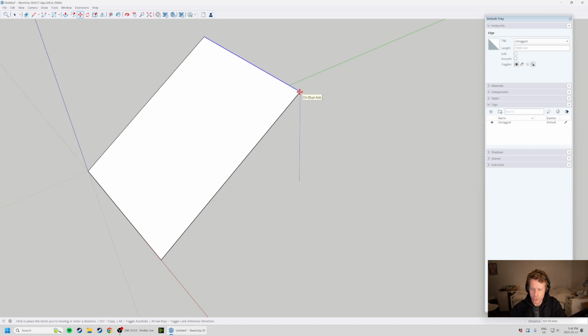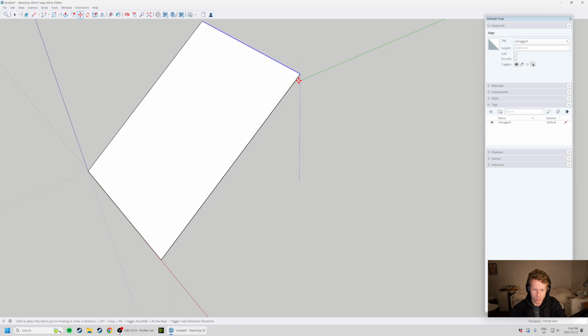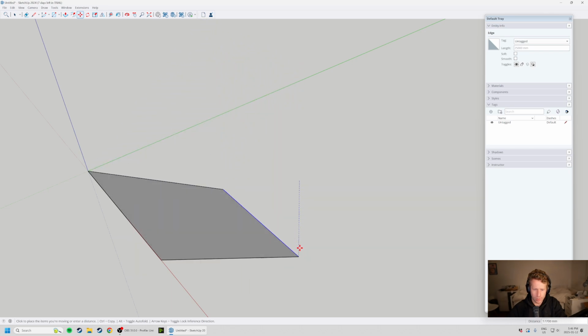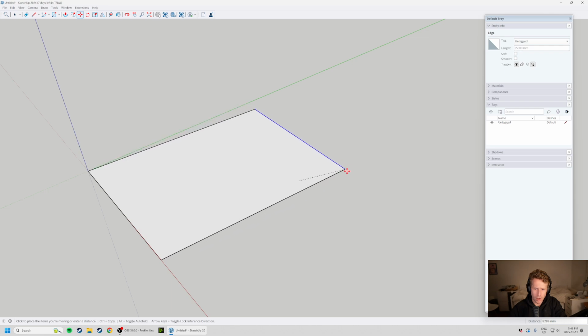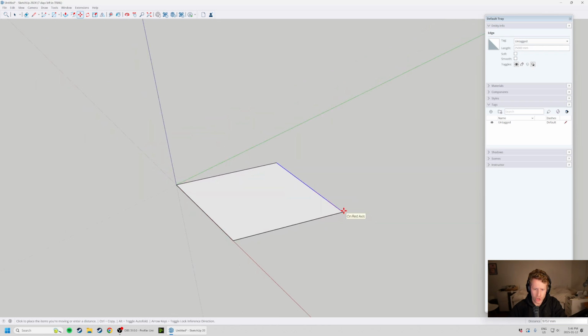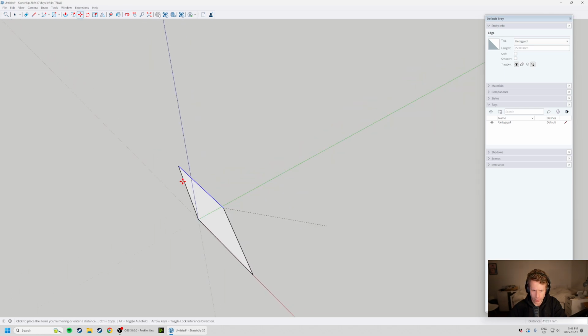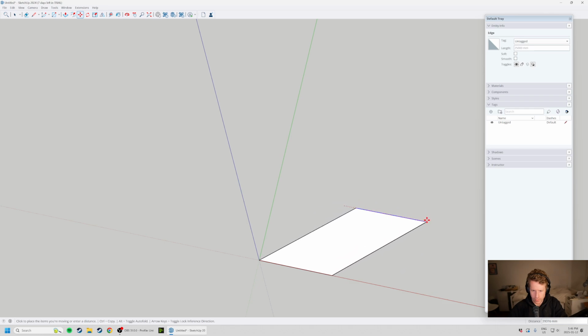And in the bottom right of my screen, you should see that little 16179 and so on. So the more that I pull up or pull down, I can modify what that looks like. It should also snap to my green axis. You can see that the axis actually turns green, so you know that we're pulling or stretching that edge along the green axis. Or you can shrink it. We can also shear it. So shearing means, if I look at this in plan, I'm shearing this whole piece of geometry. I'm literally just taking that edge and moving it across on the red axis.